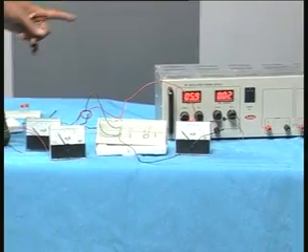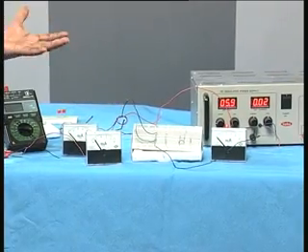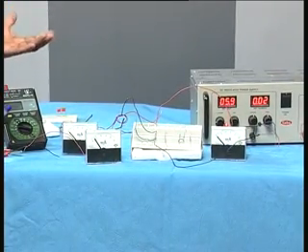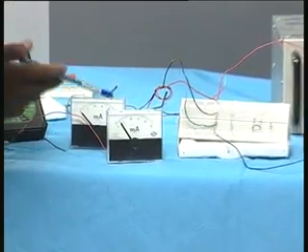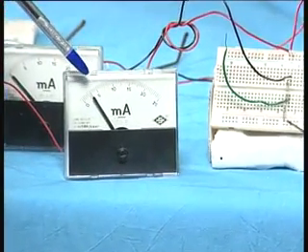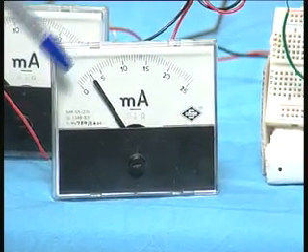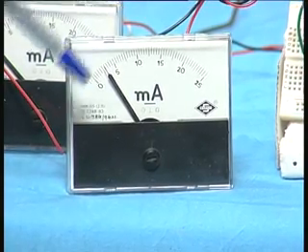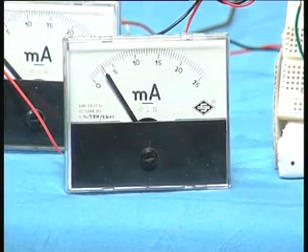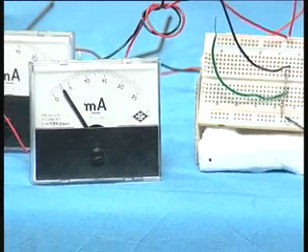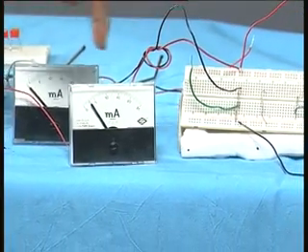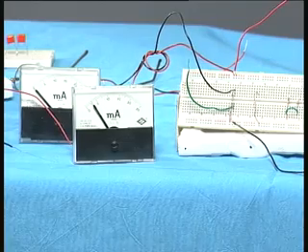So, when I have 5.9 volts, two resistors equal to 2K, 6 by 2K is around 3 milliamperes. So, you can see this bigger division is 5 milliampere. So, it is nearly 6 divisions, that corresponds to 3 milliamperes of current. So, you can see again it is following Ohm's law, and the two resistors have got the same current flowing through them, which gives 3 volts across each in this case.